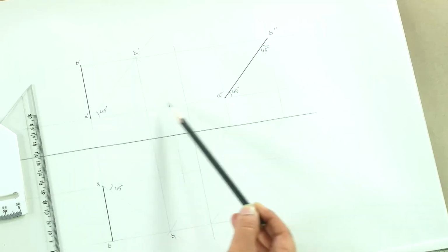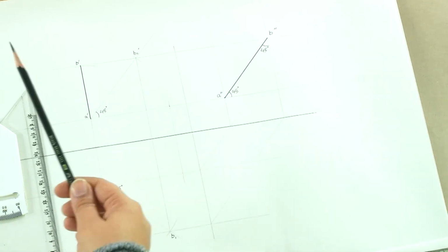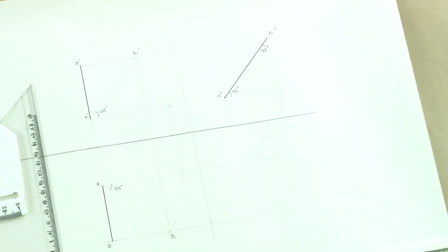Always keep this in mind that the projection lines for a point should match throughout the drawing. There should not be any ambiguity. If it is A, the projections of A will all match in either of the planes, not just in HP and VP, but also in the side planes, and then you can appropriately label it. It's as simple as that.